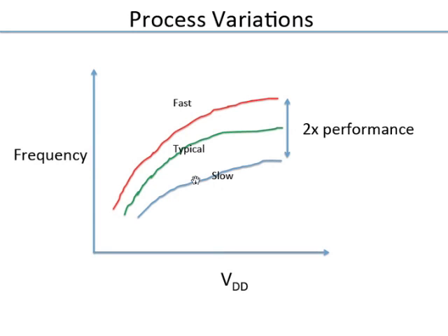But then what will happen is that you have a lot of chips which can run at the same speed of 1 gigahertz at a lower voltage. What is different in these chips is the threshold voltage. The threshold voltage is a random variable. It has a mean and it has a spread. For these slow chips, VTH is high, VDD minus VTH is low, so speed is low. Here VTH is low, so speed is high. So from fast to slow, this is the variation.